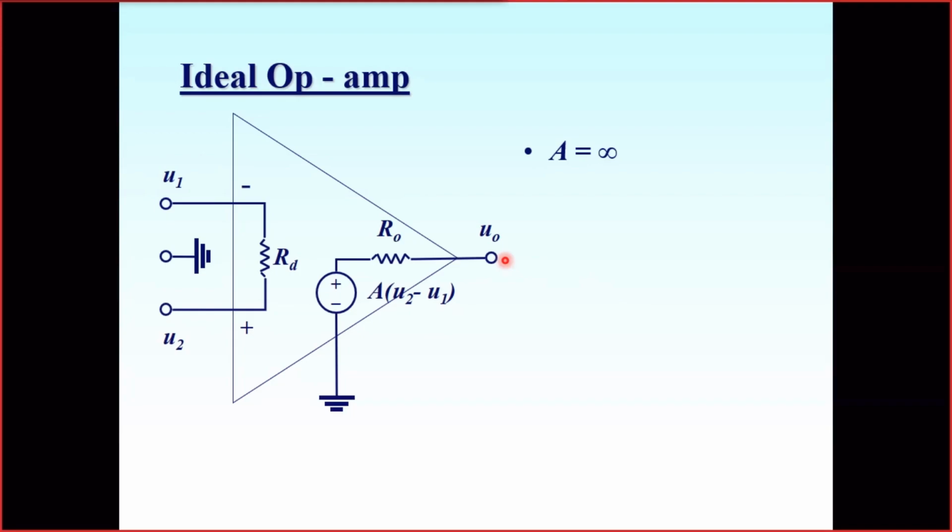So the ideal op-amp is, not ideal, but real op-amp is characterized by so-called saturation. When you have the difference in inputs high enough, the output grows until it comes to the power supply. Generally, the output of the amplifiers is not exactly equal to power supply, but it's limited by the power supply. The difference between the output and power supply line is positive or negative, maybe up to 1.5 volts.